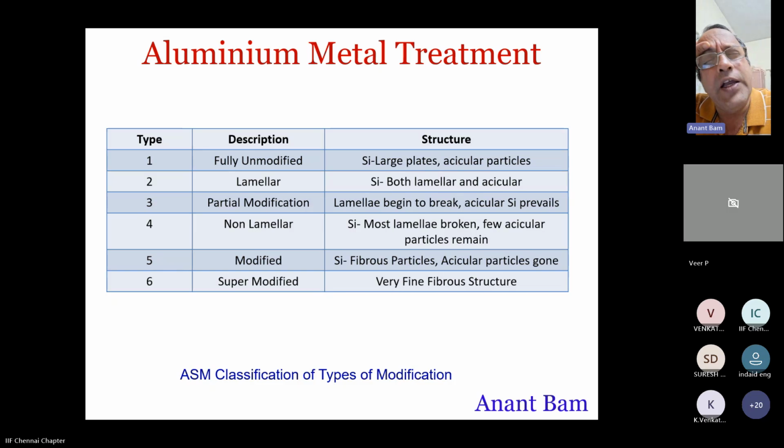There is one more mechanical property, or rather physical property, which is called electrical conductivity. There is a specific grade of castings which require minimum electrical conductivity of 33% IACS up to 35%, 36%. There are various ranges. So if you want a better conductivity, go for proper degassing. A gas-free and more homogeneous metal gives you a conductive metal.